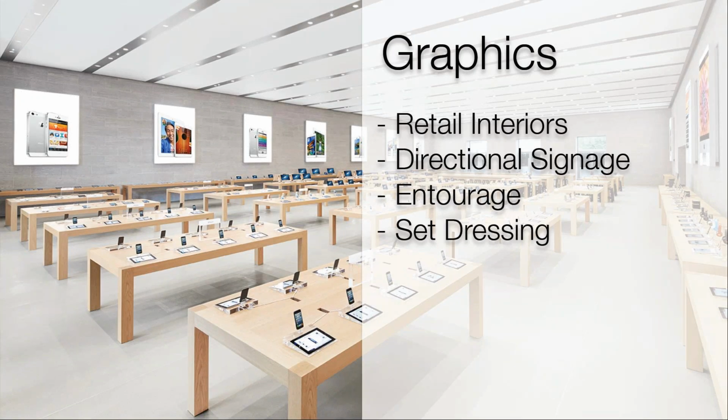However, you can keep the geometry really simple and apply an image. And the image can be marketing signage, it can be the image on a computer screen, it can be directional signage, it could be a menu board. That image could also be the appearance of an expensive piece of equipment. So instead of modeling all these buttons and dials, you simply apply an image from the manufacturer. Visually, you won't be able to tell the difference, but by doing so, you keep your Revit models nice and clean, very light, and keep all the detail in the schedules. They'll still tag properly, but when it comes to viewing those objects in Enscape, the visual fidelity will be fantastic.